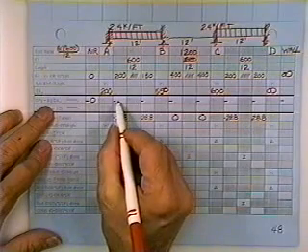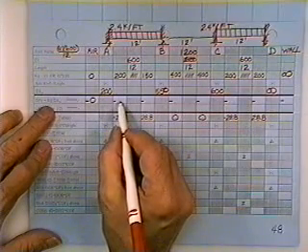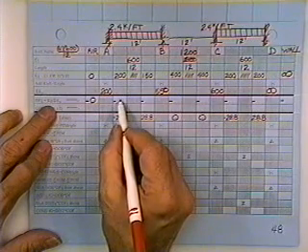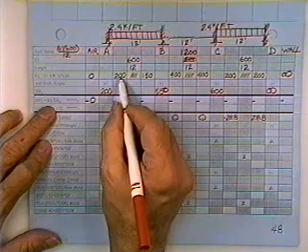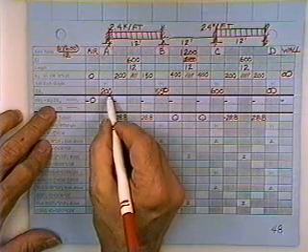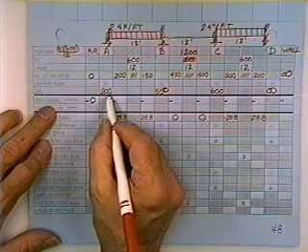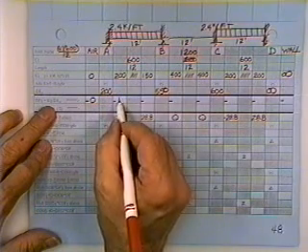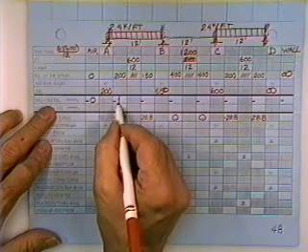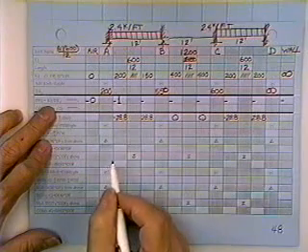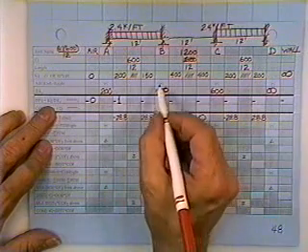Now then, for the stiffness of the next empty spot here, you go up and get the K sub ij for that member, divide it by the sum of the Kij listed just below it, and 200 over 200 is 1. I really suggest you put a minus 1 in there to remind yourself to change a sign. You'll see that in a minute.